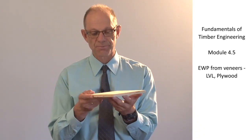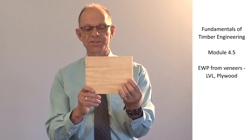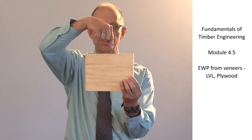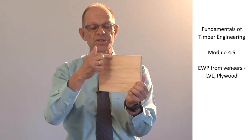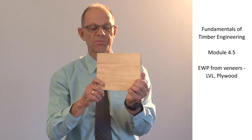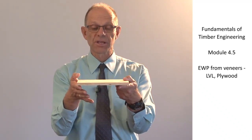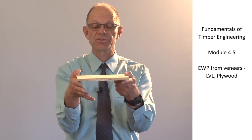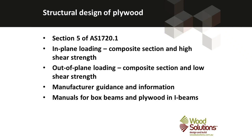The structural design of plywood considers two different variants. One is in-plane loading, where the plywood is essentially loaded as a really deep beam. So the loads for in-plane loading would be applied here, and stress is induced in this direction and that direction at the top and bottom of the sheet. Out-of-plane loading loads it very much like a floor. In this case here, the loads are treating the plywood as though it is a miniature slab. Both of them use composite section theory to analyse the plywood, and that is fully detailed in section 5 of